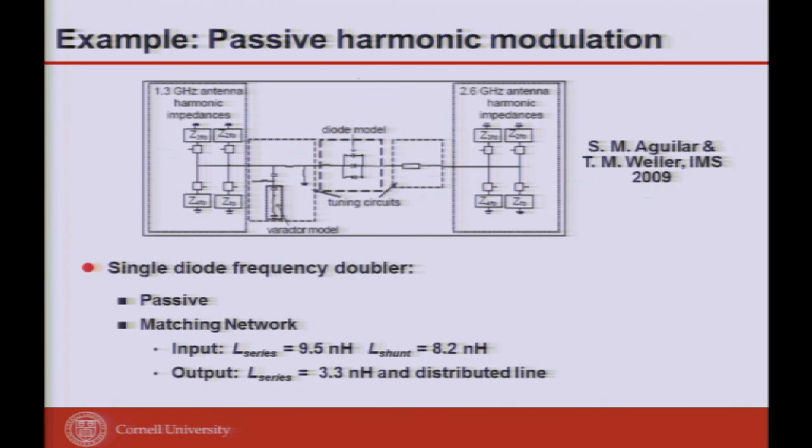Apparently the diode is a nonlinear capacitance, so you need a matching network. You need to put a matching network for that nonlinear element, and this is usually a pretty large inductor tank, both for the fundamental frequency and for the harmonic frequency. And all passive matching networks, unfortunately, are narrowband. So you have to separate the two matching networks, and you use very significant inductors to bring the impedance back to real, so that you can match to the antenna.